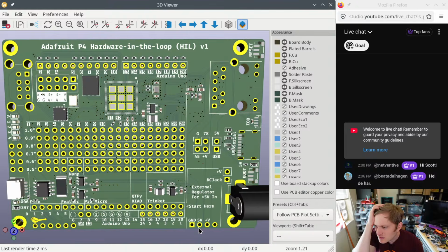Maybe the extra pins can be broken out to test points. Is there room? Which extra pins? Are you talking about CSI, DSI? Those wouldn't really help you. The extra I/O expander pins are on this header and this bottom header. The CSI, DSI, I don't think you're going to want to do them on test points anyway because they're high-speed differential signals.